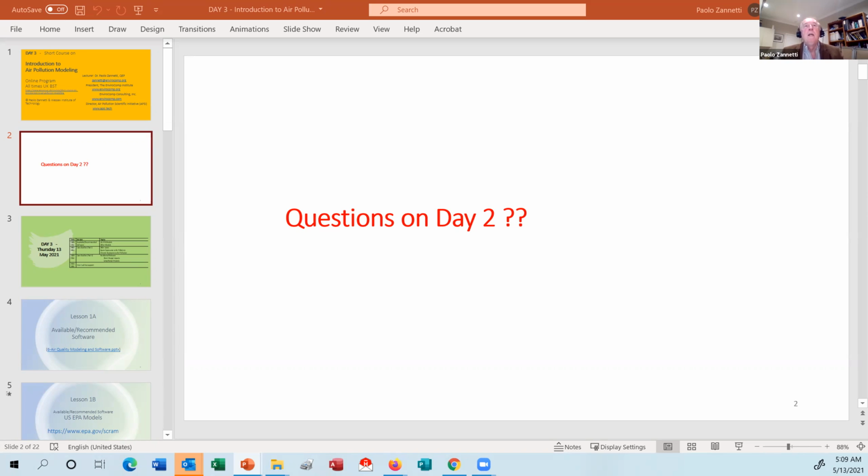Yeah, okay, if that is the question, the particle modeling is a cloud of particles, and there are many methods to calculate the concentration downwind. One method is just to count the number of particles within a volume. Each particle contains a certain amount of pollution mass, so you create a small volume, count the particles inside it, and that gives you the concentration. Or there are other methods called kernel methods. Since very few people use particle modeling today, I will probably move on and not elaborate. Maybe later this afternoon, we can go deeper into this calculation of concentration if there is interest.